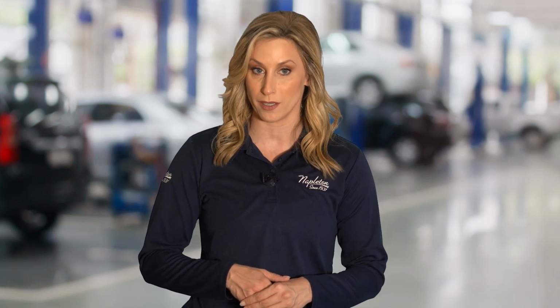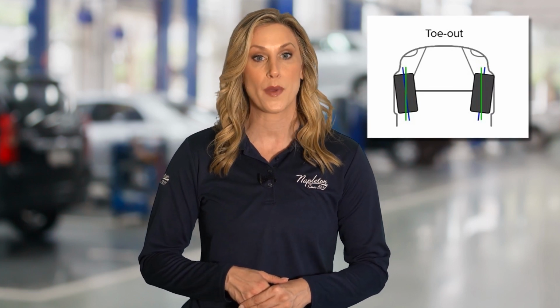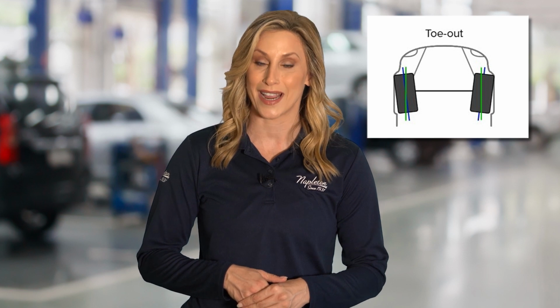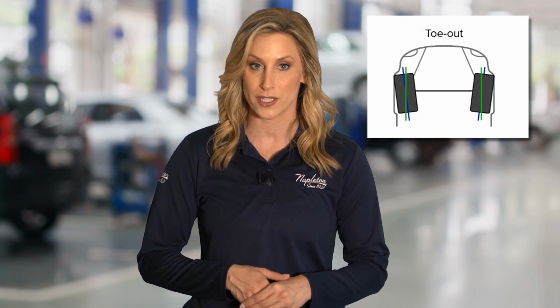As each wheel aligns itself straight ahead, the opposite wheel assumes all the toe value. As the wheels alternate between straight and toe in positions, the steering linkage and steering wheel oscillate back and forth, creating a shimmy. Toe out results when the front tires point outward when viewed from above and is also referred to as negative toe. With excessive toe out, each wheel will roll in opposite directions and neither can find a straight position. When the two front wheels are pointing in opposite directions, the vehicle wanders and requires constant steering input to keep traveling straight forward.